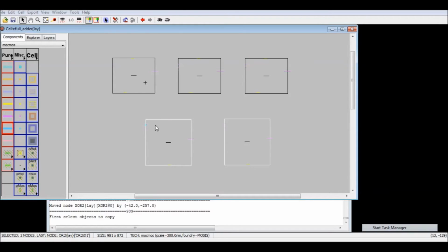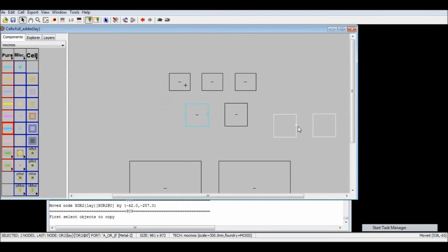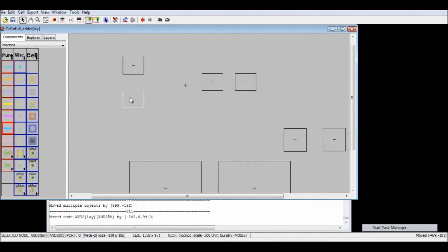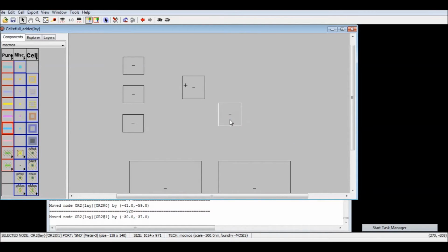Okay, so to find somewhat of an optimum solution to the interconnections between the VDD, the inputs, and the outputs, you need to use what we learned in class, which is floor planning. Now you need to draw some diagrams on paper and then try different scenarios. In my case, I think I'm going to use this diagram. Okay, it will be like this. VDD will only go right, and ground will go left.